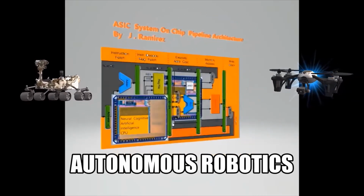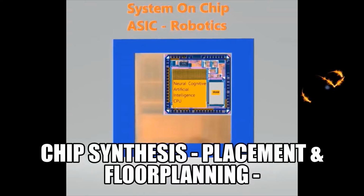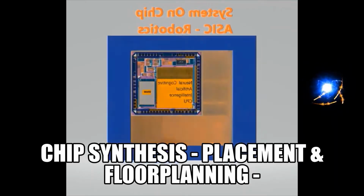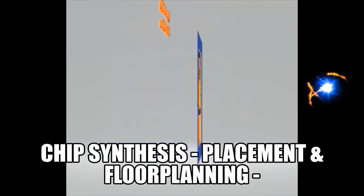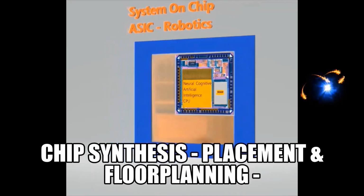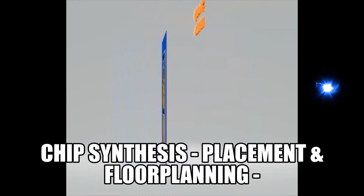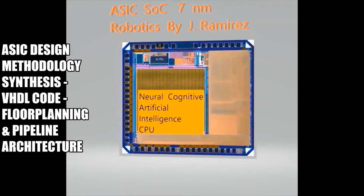Here I use the hierarchical environment. Timing-driven design is used. Each of the blocks is placed and routed separately with respect to the timing assertions. A second pass-through wiring connects the blocks together with respect to the chip-level timing assertions.